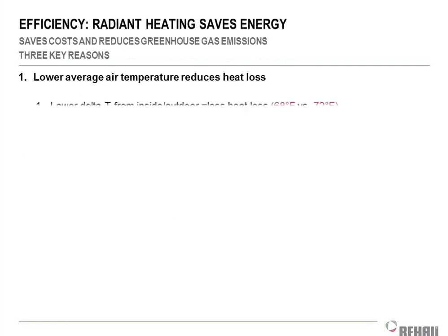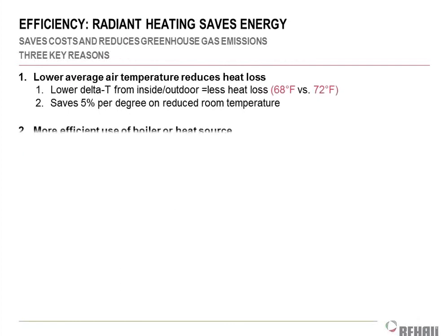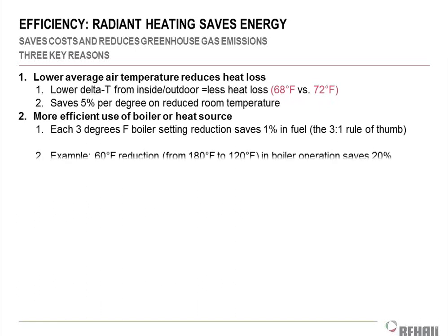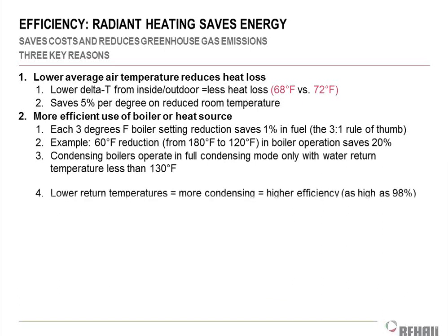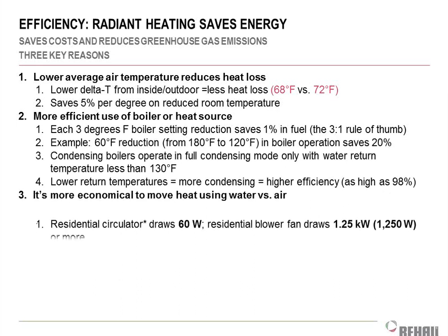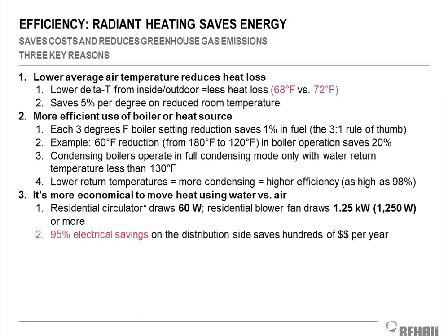All right, we already talked about how lower air temperatures in the building reduce the heat loss. Heat loss is a function of temperature differential. So the cooler it is inside, the slower the heat goes from inside to outside. So that's one of your energy saving things. You'll typically hear rules of thumb saying that every degree you lower your thermostat, you save 3 to 5% on your energy bills, right? So you hear that kind of stuff thrown out there sometimes.